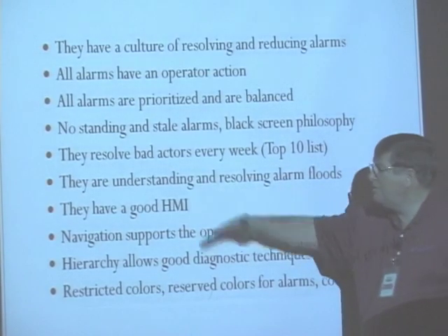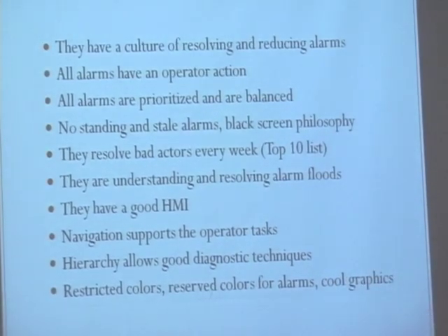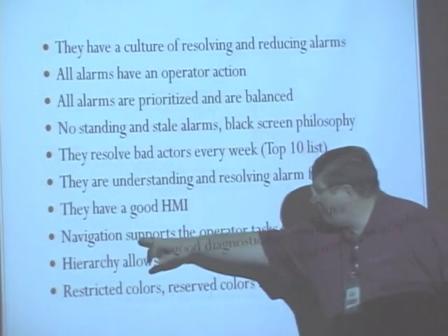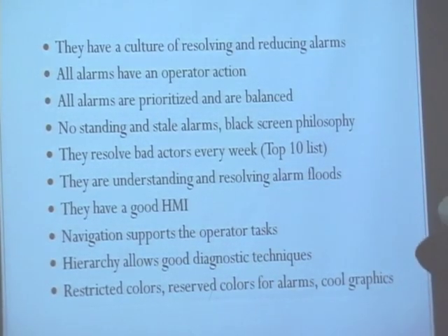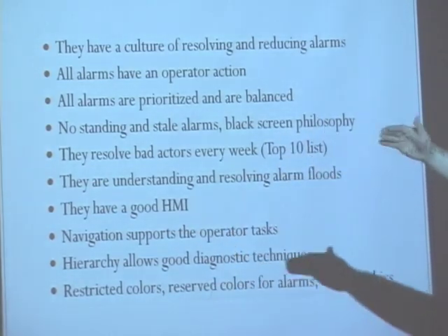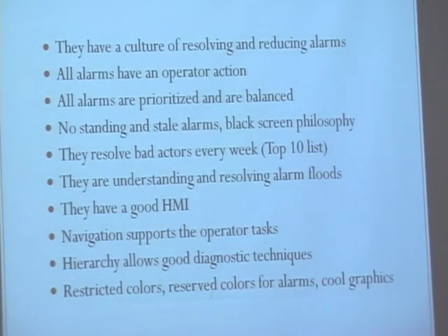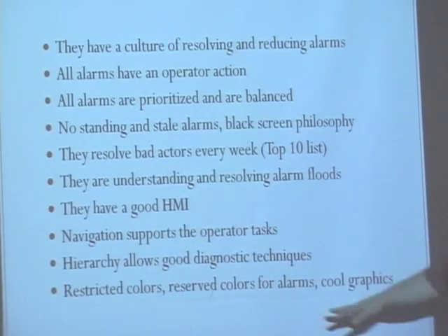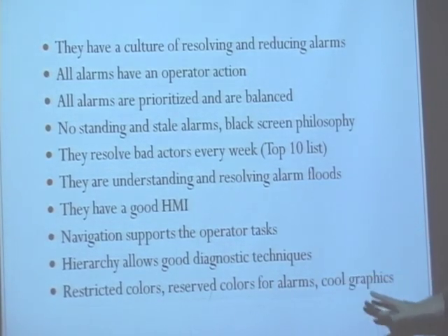They now have a good HMI because they didn't just try reducing alarms, they improved their graphical systems. They have navigation that supports operator tasks. Rather than just have a P&ID that goes from the end of the P&ID to the next picture, and the next picture, you find that operators have to jump around different screens to get information. So they have a hierarchy that's good for diagnostic techniques. They've restricted colours and reserved colours for alarms, and they've moved to something we call cool graphics.